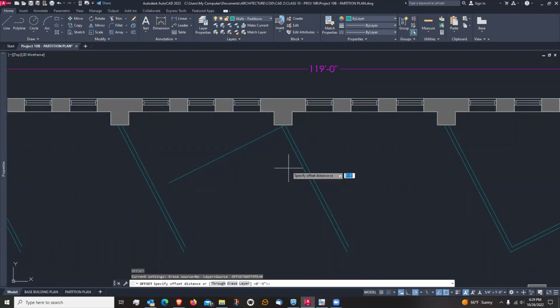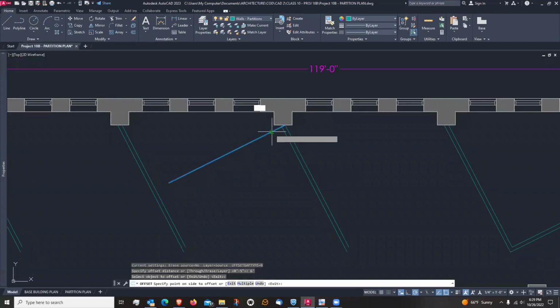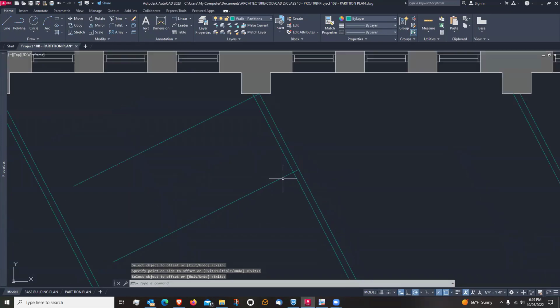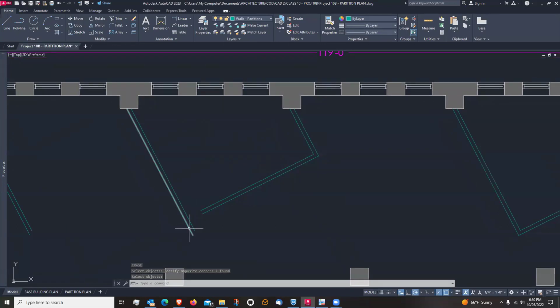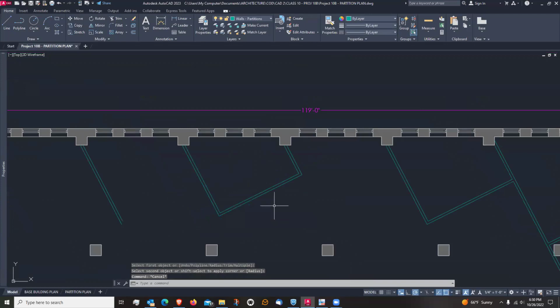How much? 6 feet. Okay, so that'll mark the outside face of this wall here. So I'll just offset that 5 inches and I'll fillet this just so I don't get confused here. And then I can get rid of that guideline. Okay, good. And then this sort of just extends to there, or actually it just fillets. So I'll just fillet that. I think that looks right.